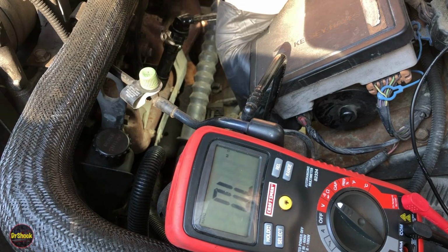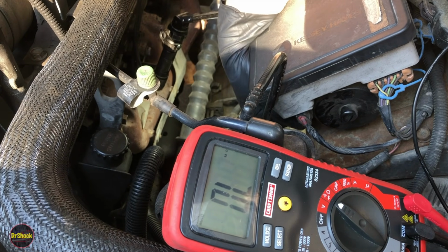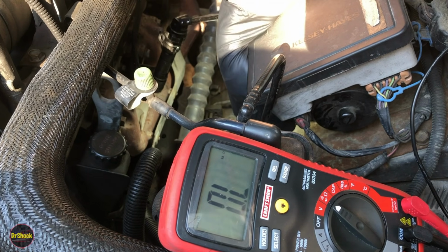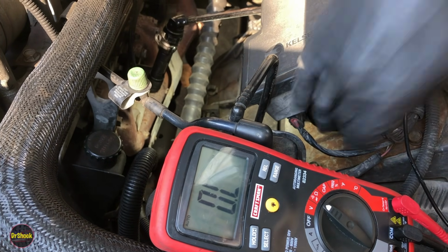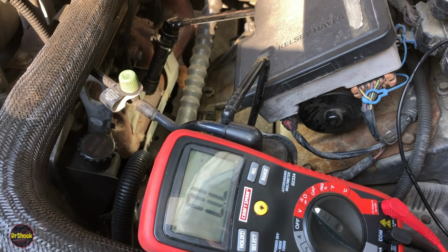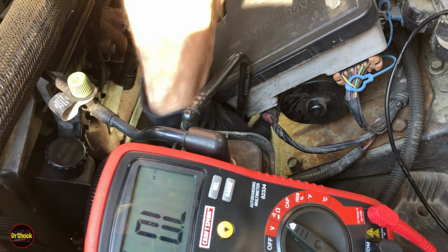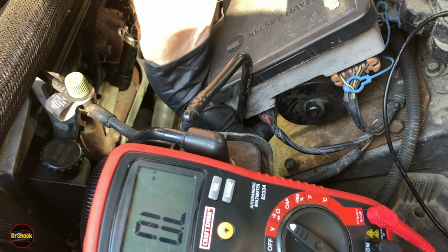Okay, so that tells us that the pump is not dead. If we had gotten less than 0.1, we would have an open. And if we had gotten more than 1 ohm, we'd either have carbon buildup or corrosion on the brushes of the motor. So that's not what we got. So we're going to move on to this connector C3 on the EBCM and pop it off. Same kind of little tab. You lift up on.